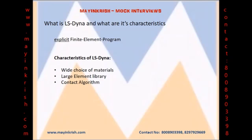Coming to the characteristics of LS Dyna, it has a wide choice of materials, a large element library, and contact algorithms. The wide choice of materials includes plastics with kinematic and isotropic hardening, strain rate dependency, temperature dependency, then foam, composite material, rubber, viscous fluid. We can create our own materials by using the Fortran interface.